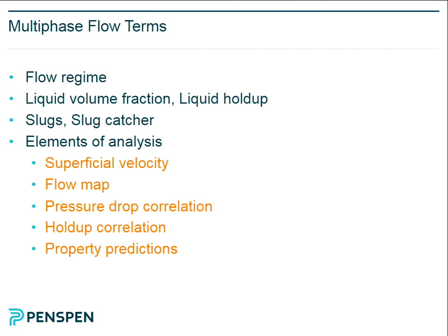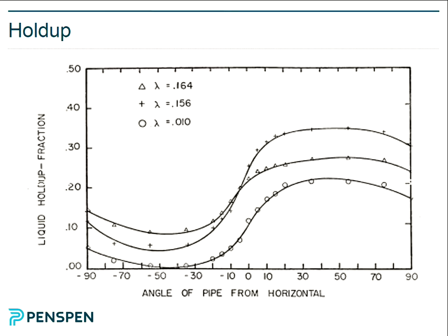Okay. Generally, you can think about multi-phase flow as horizontal regimes and vertical regimes. And these are the horizontal ones. They're split into three groups: segregated, intermittent, and distributed, basically. So segregated is like horizontal stripes, if you like. Stripes going that way along your pipeline.